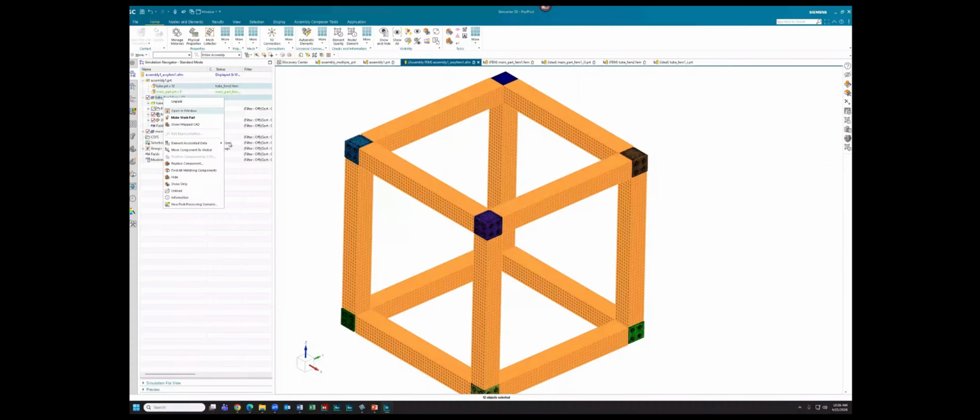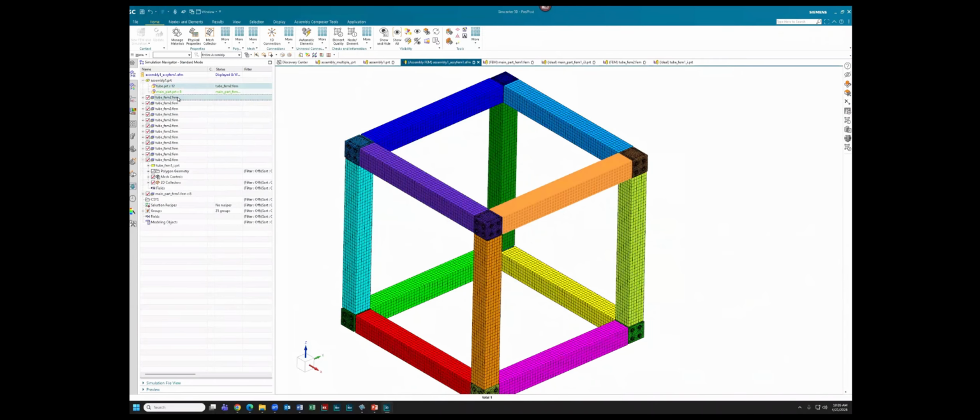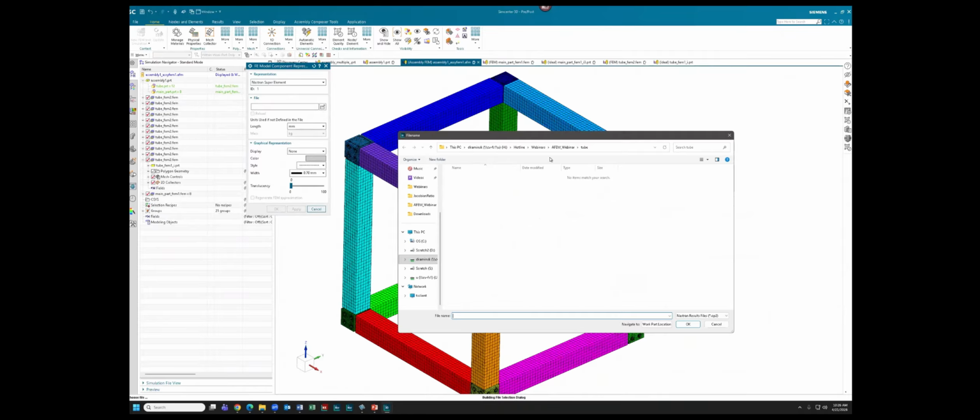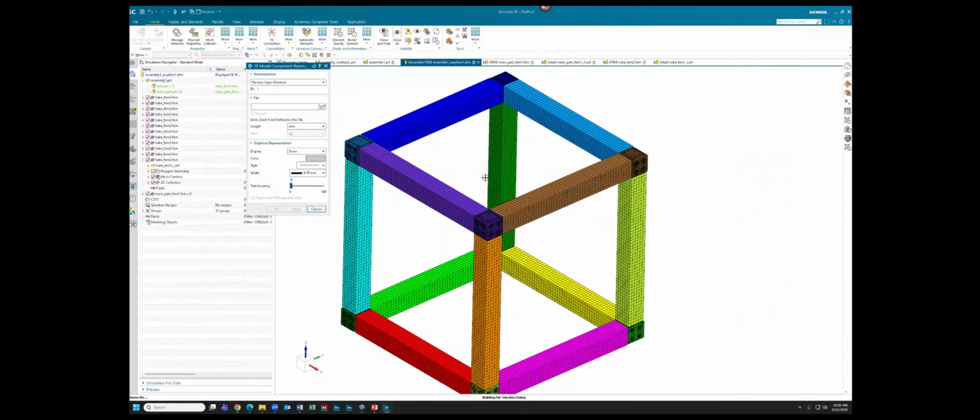And now let's talk a little bit about what if you want to change your representation of components within the assembly FEM. So for example, maybe for one of these instances of these tubes, you actually instead want to use a super element representation. So you can do that easily. So this will just take a second to import.